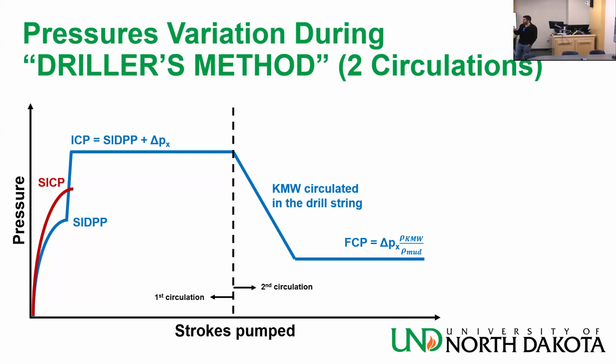Remember, the actual fluid density is completely unrelated to the FPP. You can have gas, low density, at a very high pressure. You can have brine, very high density, at extremely low pressure. FPP, kill mud weight, and the kick are very, very different.